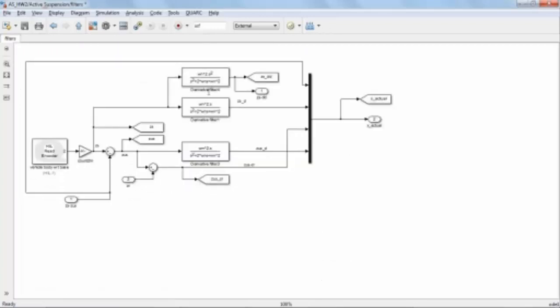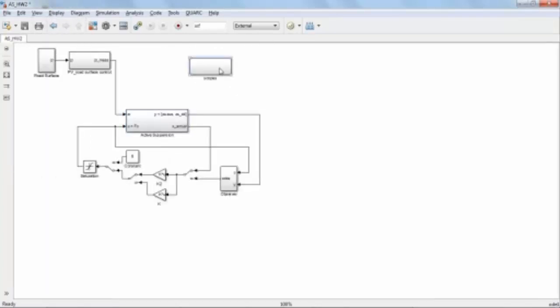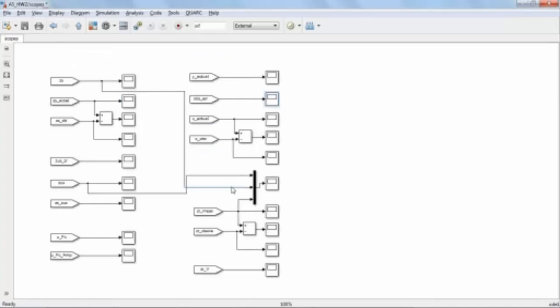We're using a lot of high-pass filters to get our second derivative terms to reconstruct our signal here. Using high-pass filters works quite well, but they always have the issue that they amplify noise quite significantly. So our output signal will not look too nice and will not be smooth. And usually, if we can get a smoother signal, we would expect something nicer to see.